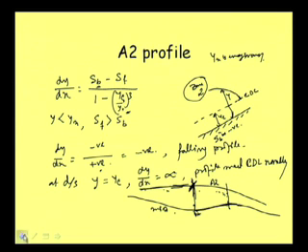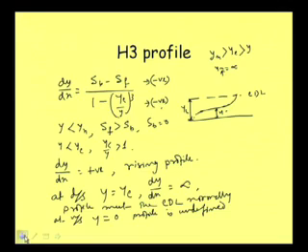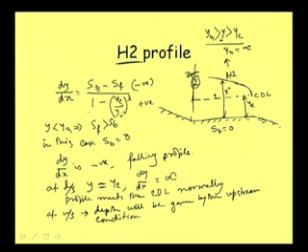Similarly, in horizontal slope also, when we were discussing that part, what will be the upstream depth? That will depend on the length of this horizontal portion, because we are computing from this side, and this way we will be arriving at a point. And then at upstream what will happen? That will be decided from this particular depth. We will go like that. And of course, some other combination may be there if this slope is a steep slope. Suppose supercritical flow is coming in this part. Well, that part we will be discussing later.